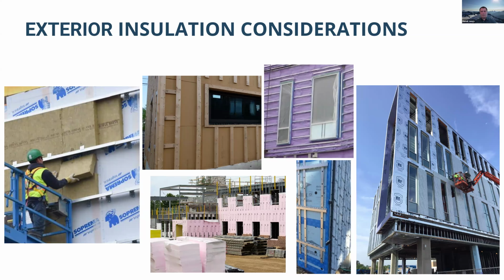But the air barrier itself is what controls air moving through the building enclosure. So we need them. They're code required. They also improve resistance to water intrusion by eliminating essentially a hole through the building. There are lots of other benefits as well.